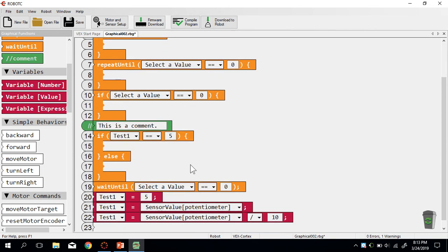Because most sensors give you what I like to call raw data. So it's just a number between some raw value. For the potentiometer, I think it goes from 0 to around 5,000. Now the potentiometer can spin from 0 to 180. So if you take that 5,000 spread and divide it by 180, then you know how many values per degree.